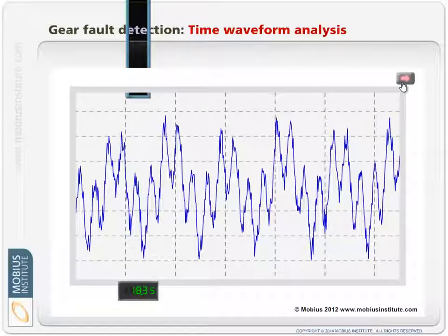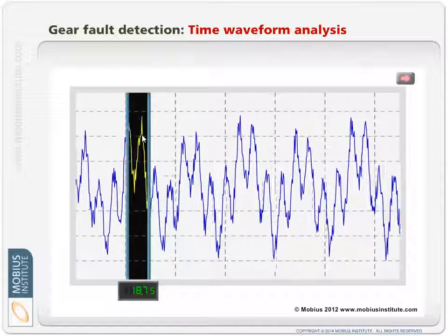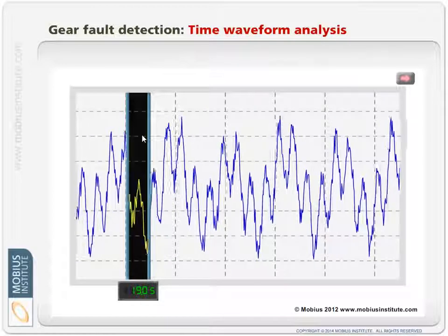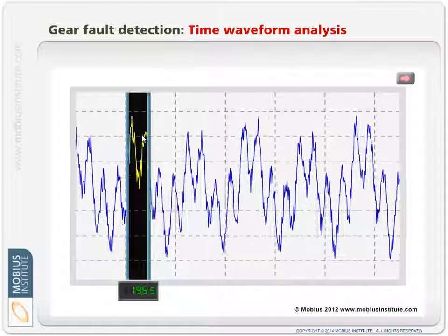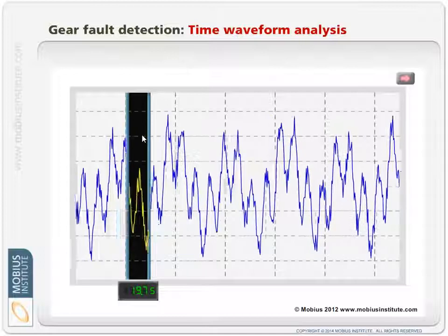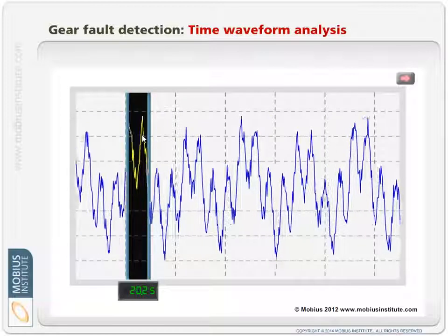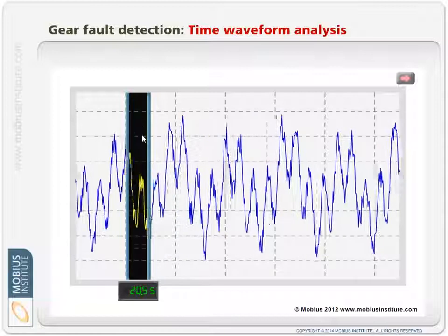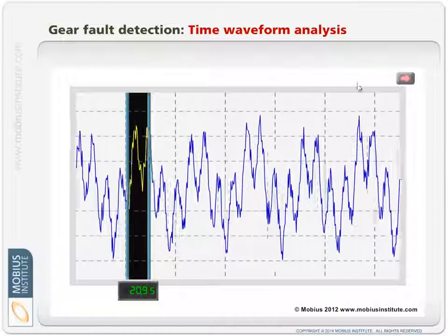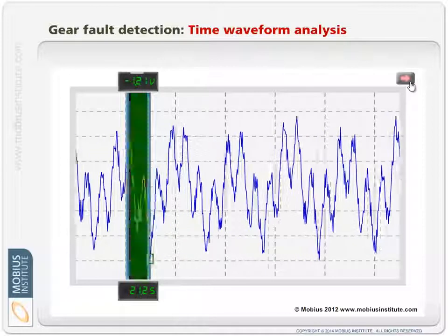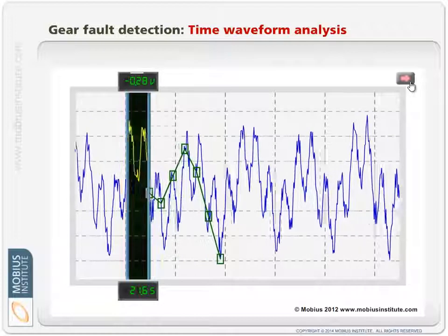Now I'm going to come along with this analyzer, and what it has the ability of doing is, at certain time intervals, it's going to say, what is the voltage now from my accelerometer? The accelerometer is sensing that vibration on the gearbox. And there are issues we could talk about with the mounting resonances and the response time of the accelerometer and all sorts of things. So the analyzer says, I'm going to take a voltage reading now, and so on. You can see them.